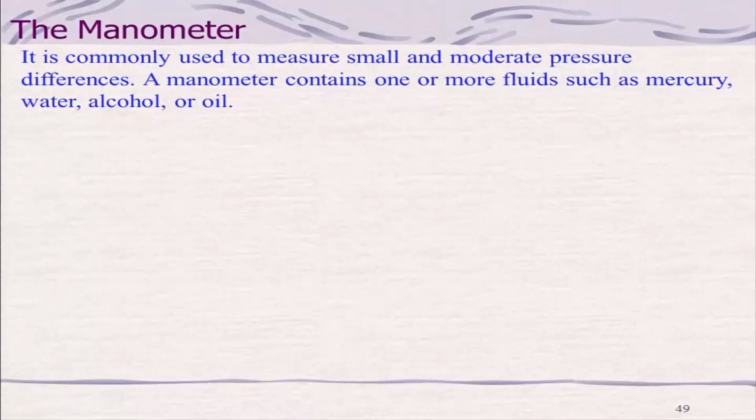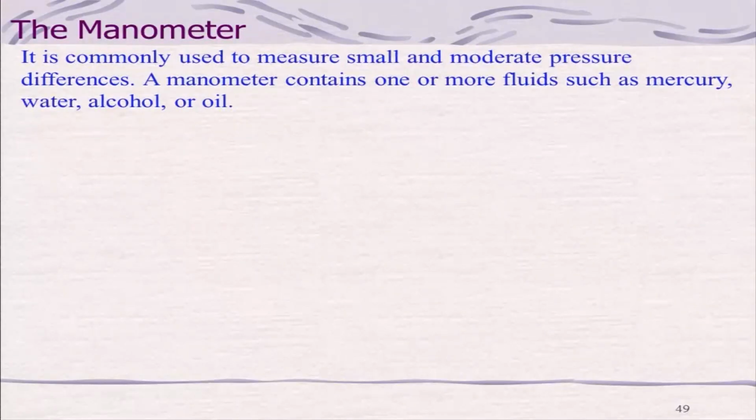So, whenever we talk about it, we need to measure pressure. I told that there is a gauge which is being used. Let us look at that. This is a commonly used manometer. You might have solved a lot of problems on manometers before during your JEE exam, am I right? And it is basically commonly used to measure a small to moderate pressure difference. Like here we will be measuring the pressure difference. You can think of pressure difference as a gauge pressure.